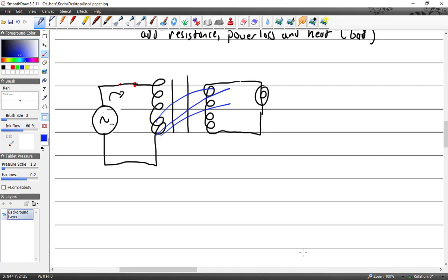It's the same thing as moving the wire in a magnetic field. Now we're leaving the wire the same and just moving the magnetic field. Build it up, pull it back, build it up, pull it back. So not only are you pulling it back, of course, but you go the other way. It builds up one way, and then it changes polarity and builds the other way. So it's constantly cutting across this secondary system, and this light is just always going to be on.